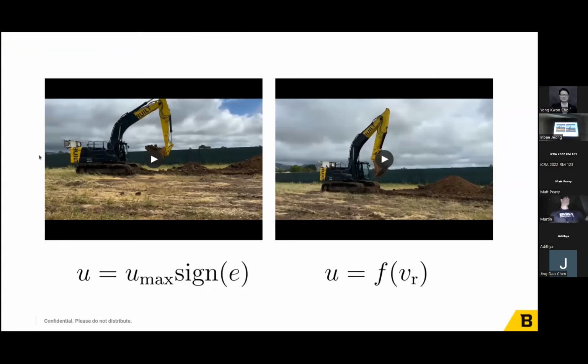We just want to uncurl the bucket as fast as we can. And then when we have done that, when it's uncurled enough, then we want to just stop. If we stop abruptly, that's only a good thing because it allows us to shake off some dirt. So it's a perfect use case for bang control. It's just 1 or 2 lines of code.